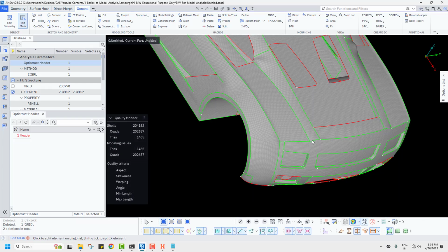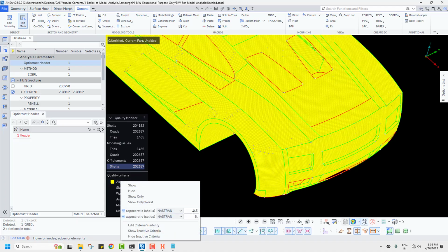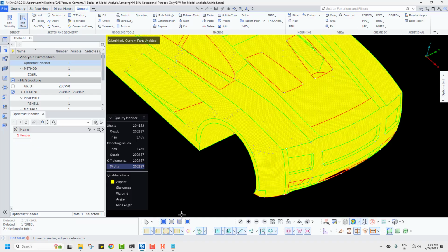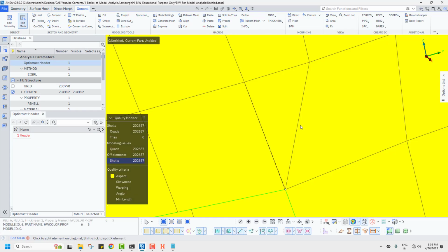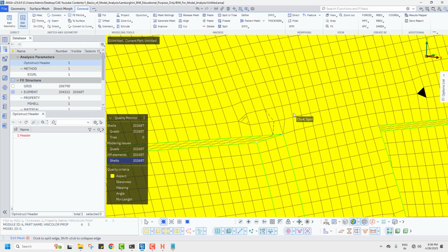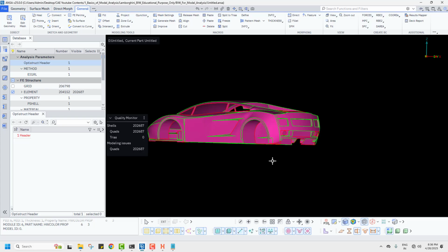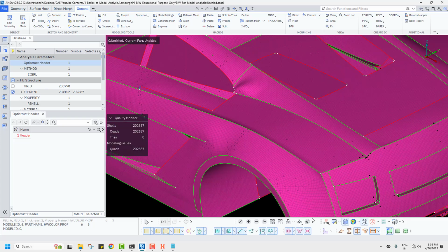The thing is, I have cleared some issues, but for some reason it is not giving me the aspect. What exactly it does is, if you keep it at 0.2 here, with respect to that it will search only for the needle elements in your model, and if you select the off elements, you show only the worst, and it will take you there and try to fix it for you. This is how it works. Now this is fine, no issues at the moment. Later on I can show that function in the next session also.